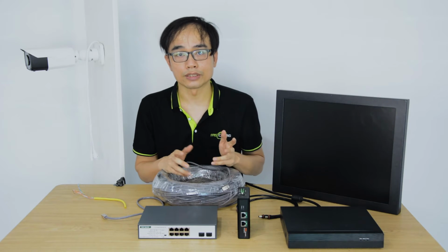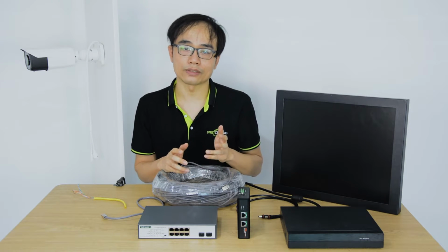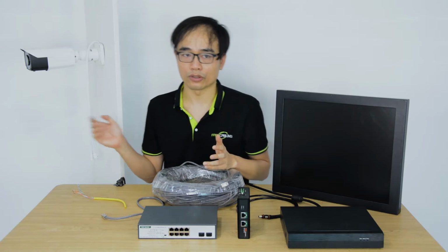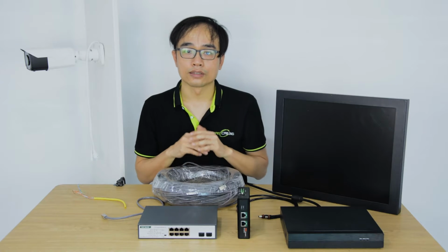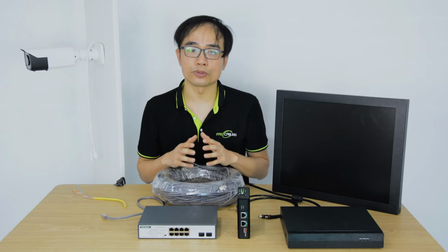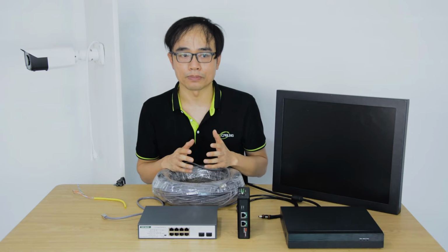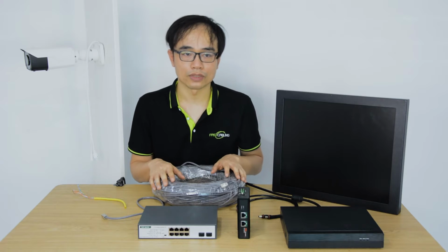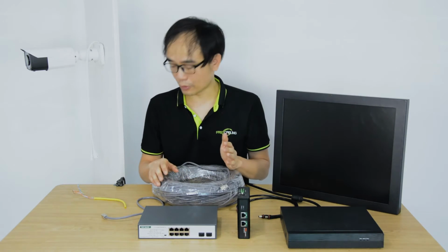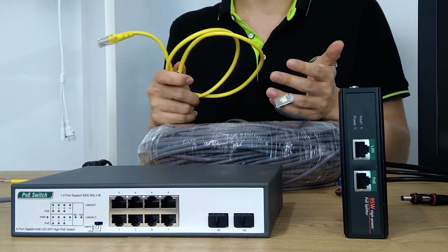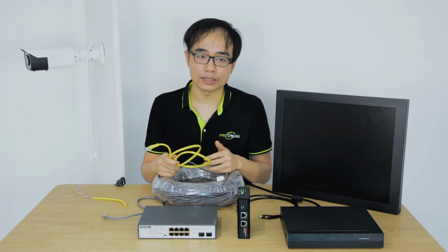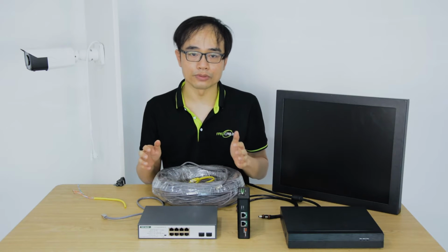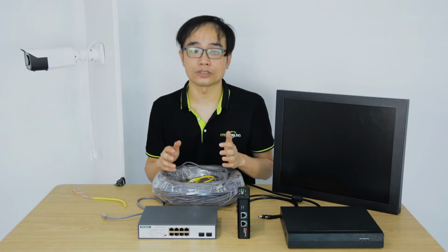So what is the exact power budget for our front-end device while we are using the new PoE? It's around 72 watts. I know I said 95 watts, so why is it only 72 watts for the camera or for our IP device? It's because power loss was considered while the IEEE 802.3bt standard was developed. There's always power loss in the line, converted to heat. Even with only a 1 meter Ethernet cable between the switch and your IP powered device, the maximum power will still be 72 watts. The PoE chips on both sides will negotiate and come up with the maximum power budget.